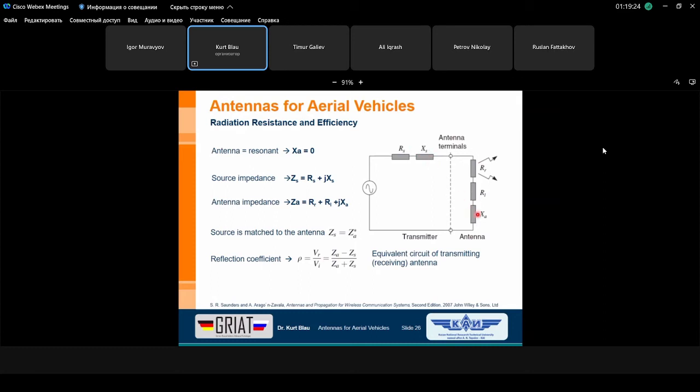For instance, if you have a capacitive imaginary part, then this should be an inductive part, so that both parts, also from the magnitude, can compensate each other. Then this minus j plus j is 0. And in this case, we also speak about resonance. It's the case for a resonance circuit. And this resonance circuit has no imaginary part, has only real parts because of the losses we already discussed.